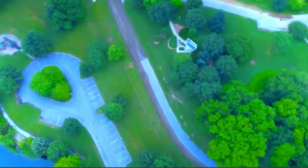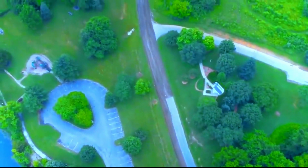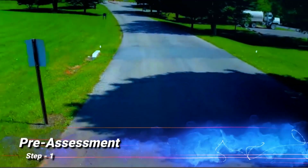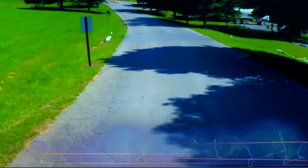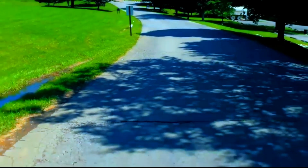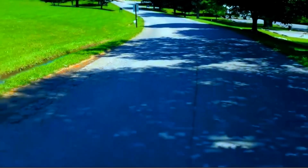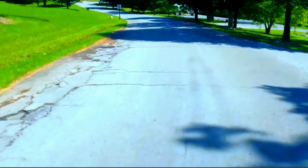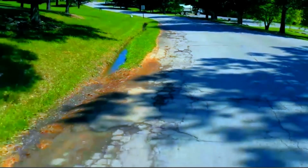But how is it done? Let's go step by step. Step 1. Pre-assessment and planning. Before starting the process, engineers assess the condition of the existing road, checking for cracks, strength, and drainage issues. The required depth of reclamation is determined, usually between 150 to 300 millimeters, depending on the road's condition.